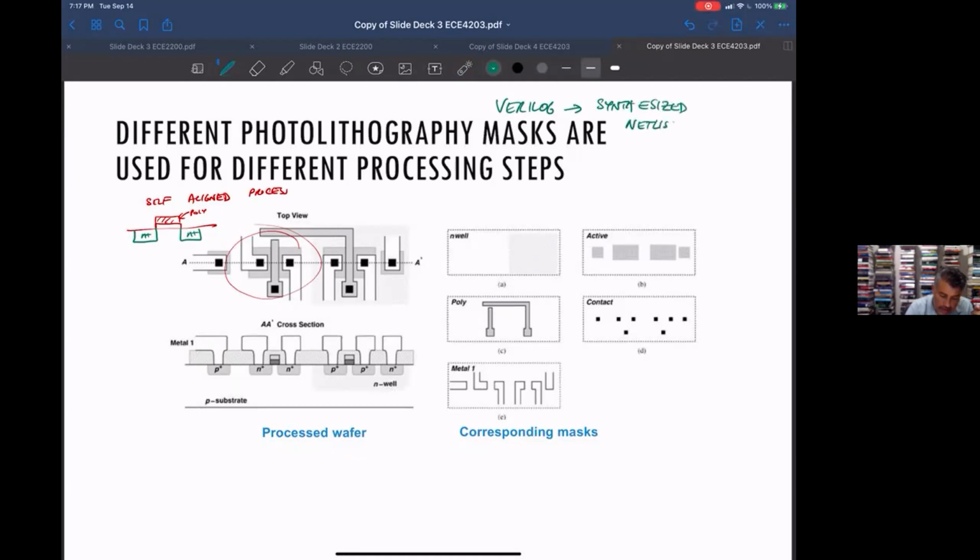netlist. So at this level, Verilog, I don't know how many of you are familiar with it. It sort of looks like C, but it's got hardware components. Like it understands what you may mean by things happening simultaneously, or latches or flip-flops. So at this point, it looks like C-ish code. At this point, it looks like schematic level stuff. And then this goes to place and route. So at this point, transistors get placed.